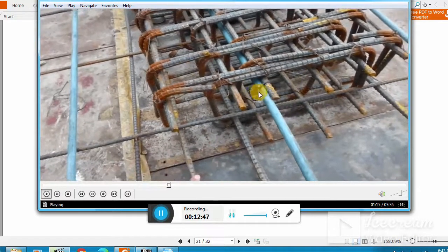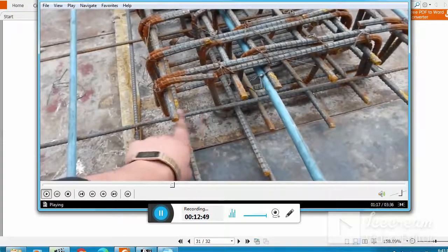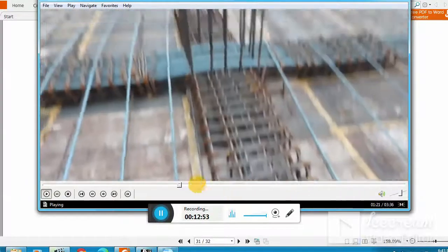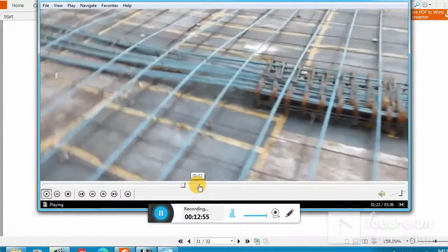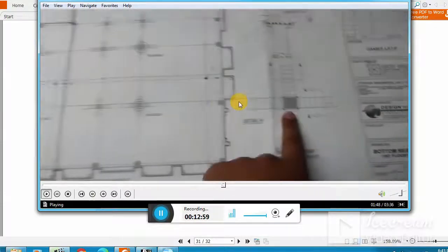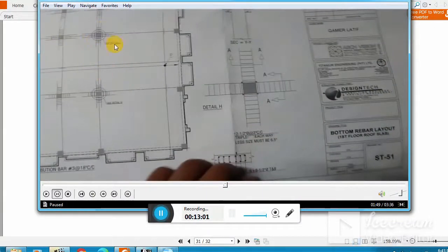So we have to find out the spacings of these bars, okay. And the spacing of these bars is simple. We are just using the shear formula, as we already explained this formula, you already know it from the shear design of our beam. Here you see the drawing of the integral beam, and it looks like this shape. And here you see the specification: you have to use 12 rings, number 3 size, at the rate of 3 inch center to center.